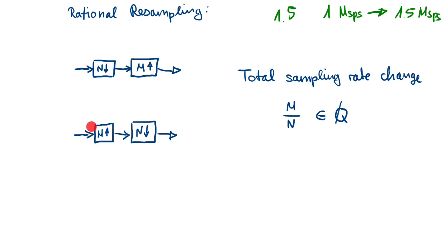So therefore, you might choose this approach: increasing the sampling rate at first, and then dropping some of the information. So here you add more information to the signal because you increase the sample rate, and then here you destroy some information to get a decimated output signal. But this comes at a drawback that you have a quite huge sampling frequency here.